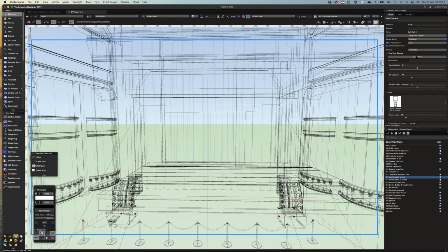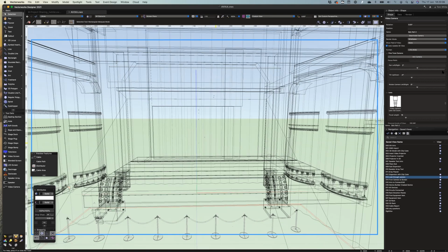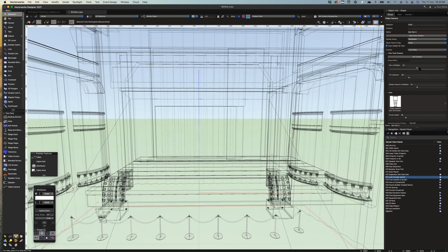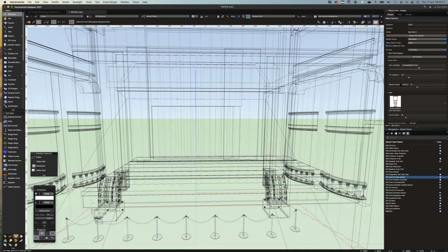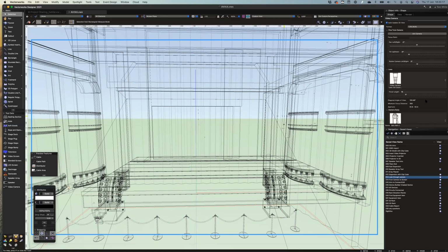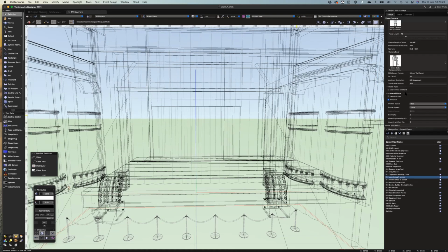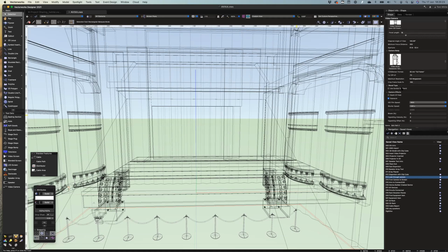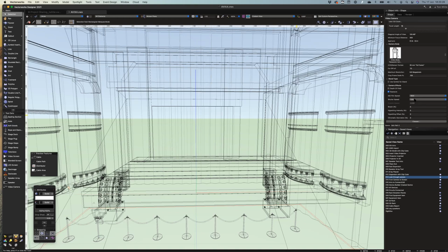Now I can also focus the camera. I can click aim camera and click on the center of the object I want to focus on. Or I can pan it around, for example. I can zoom, etc. There's a whole host of things you can do with this, including if you're really trying to get nice rendered images out, you can use the camera tool for this, which works really well. I often tweak some of the exposure settings just to allow a bit more light into the shutter, which is nice. And playing around with the bloom and vignetting is really nice as well. So it's really easy to get some really nice looking images.